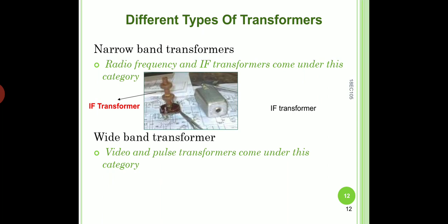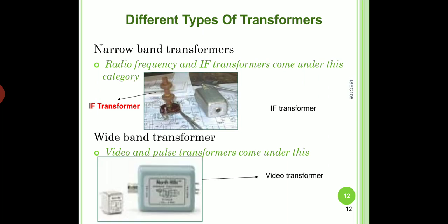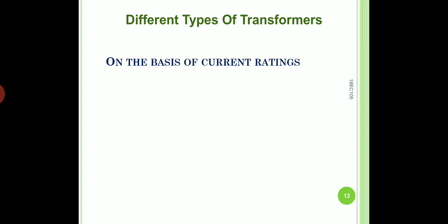See here also, because the thyristors work at high voltages and peak currents, hundreds of amperes, thousands of volts, we'll be using the transformer mainly for isolation, and then also we need to apply the signal to the next stage. For that purpose we'll be using these video transformers. They look like this. Let us see one more model as well.